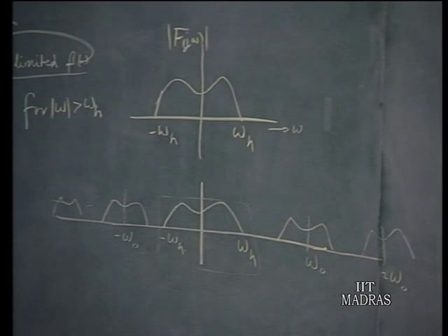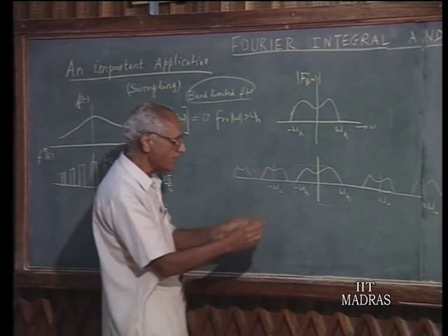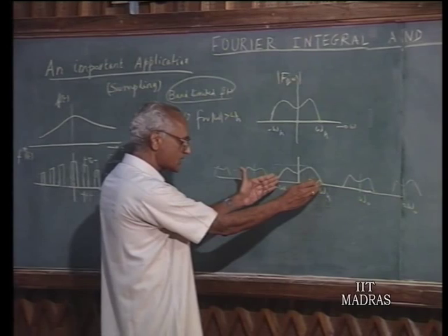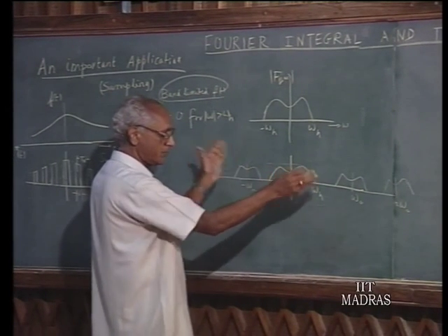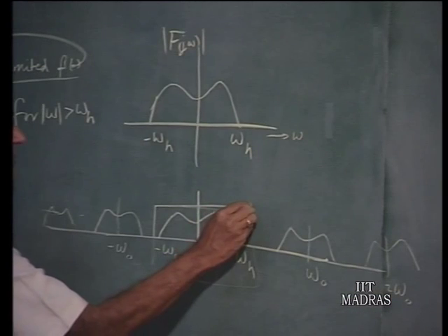This interleaving of messages over the same communication channel is referred to as time multiplexing, and this is a very common occurrence to effectively utilize a communication channel to send several messages which are inherently band limited in character. Now, you can see, in order for us to be able to lift this section of the spectrum and remove the others, you must have your low pass filter characteristic something like this.